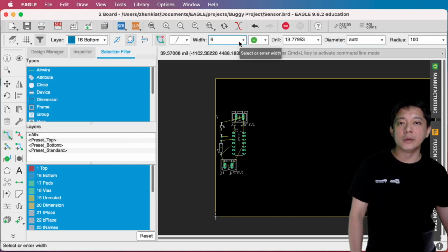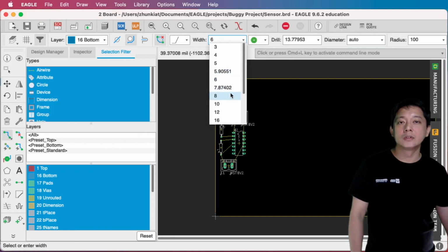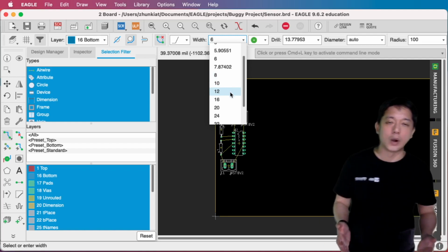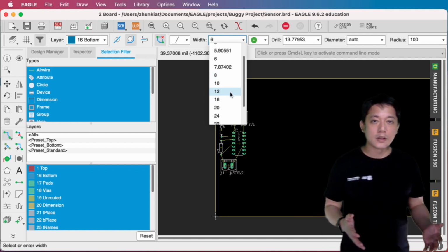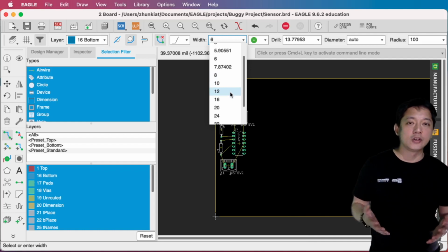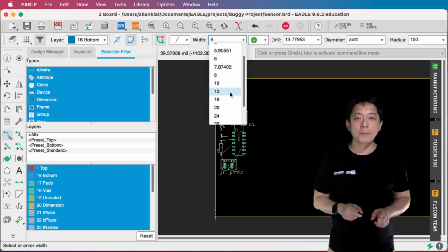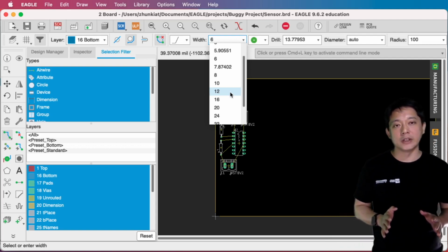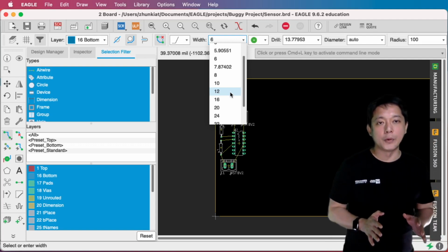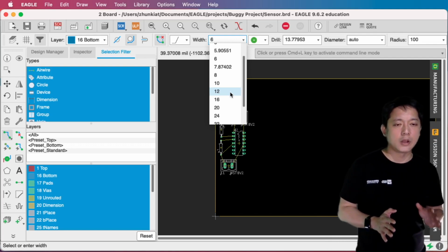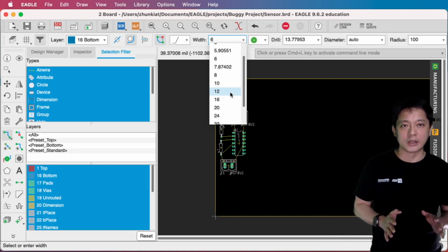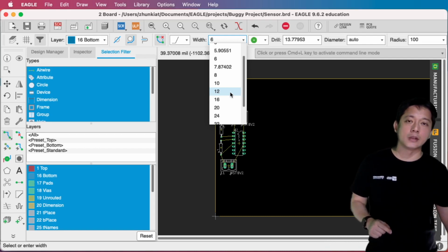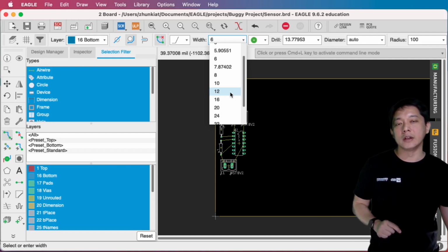You'll see this in mils. So you can go online and do a calculation of how much current you want to pass through that track, and you can actually calculate how big the track width is. The PCB board that we are using, the copper thickness will be 35 micrometer. So the thickness will be very small, but you can use that to calculate the width that you need.